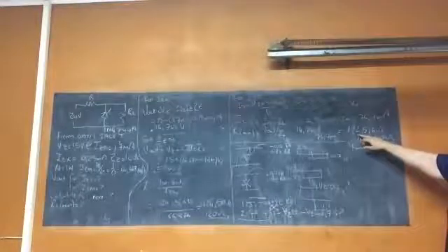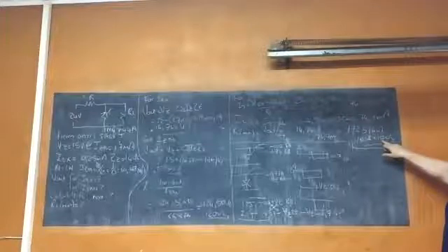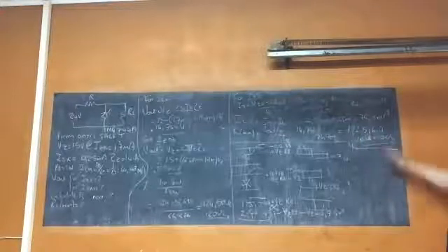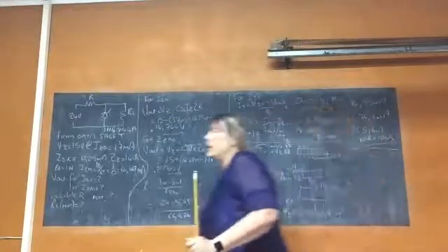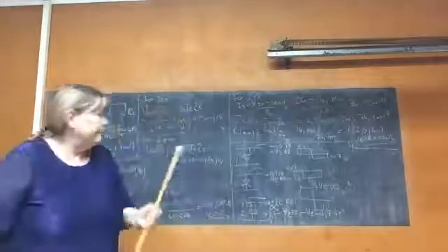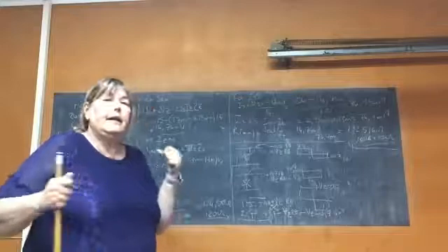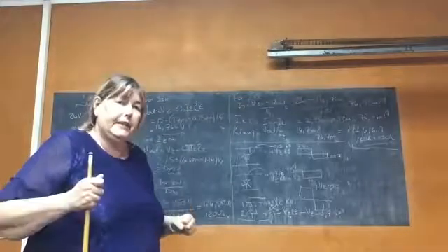And then there's 10 ohms. Because there's no 190, there's no 200 kilo-ohm or ohm. You get 180 and a 10 ohm, then you end up with 190 ohms. And that's the nearest value you can have for your minimum load resistance. And now, this is the same as the diode clipping circuits.